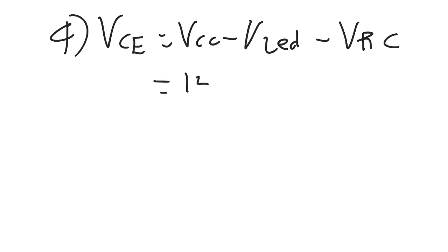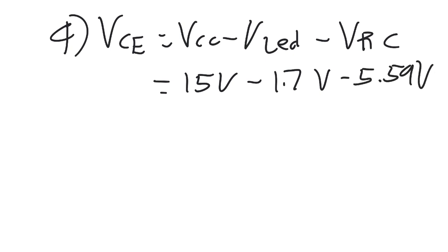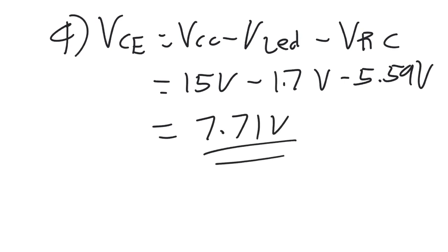Okay, depending on the color of the LED and how much current is flowing through it, roughly an LED has 2 volts across it. Could be as low as 1.5, maybe up to 2.5. Anyway, you can get that off the data sheet for the LED.